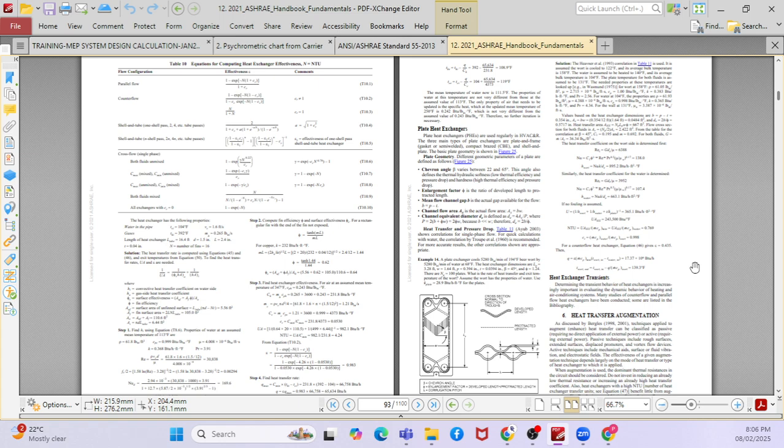Yes, this is applicable for all the products. Like you have a pump, when you do the pump flow rate, what is that? GPM equals TR multiplied by 24 divided by delta T, right? Yes. But when you go with a different pump, there is a different efficiency, right? Efficiency also matters. Depending upon the manufacturer, you will choose which efficiency.